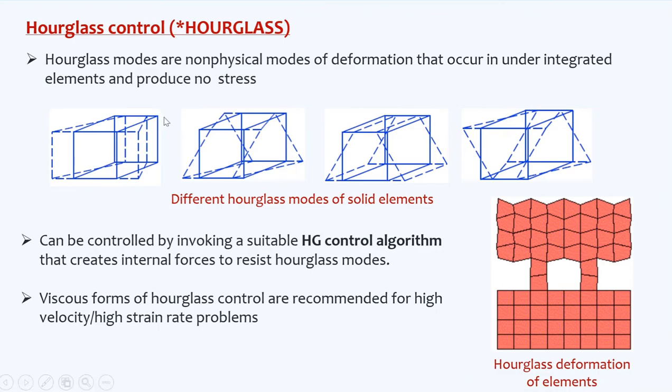Sometimes the elements will deform in such a way, like I've shown here, that at the center where your integration point lies, there will not be any deformation.